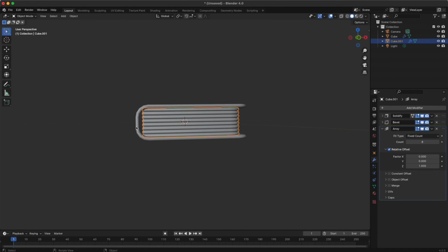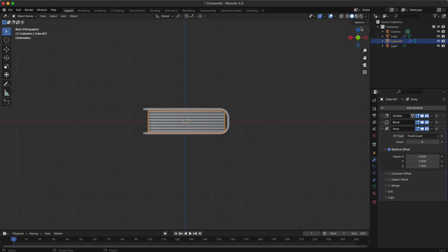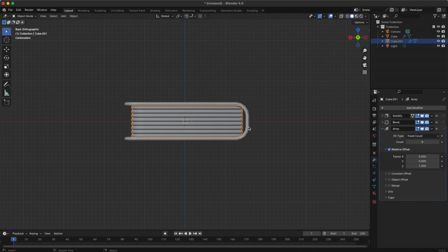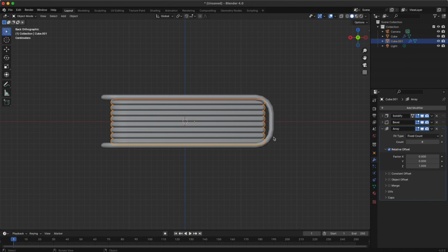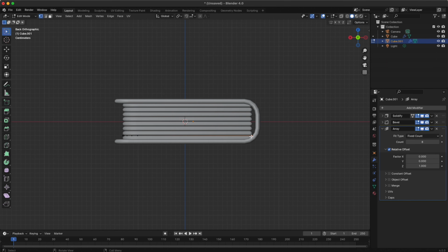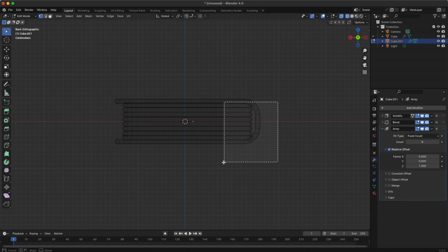Now our edge here doesn't look quite right because the pages aren't going to the spine, so we'll press X over here on our way to move around the 3D viewport, the window, and we'll scale in a little bit. And we want to move some of these, so tab into edit mode, and we're going to press 1 to go to vertex mode again. To make sure that I've got both vertices, I'm going to deselect that, press Z, and press 4 to go to wireframe mode, and then I'm going to box select that.